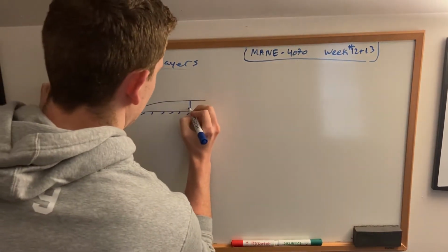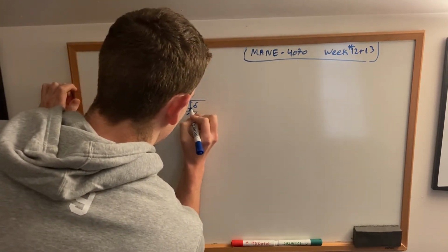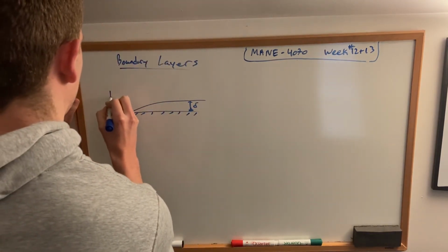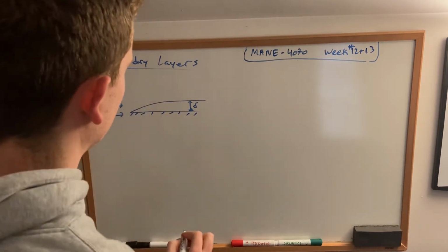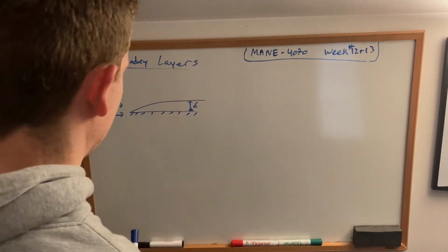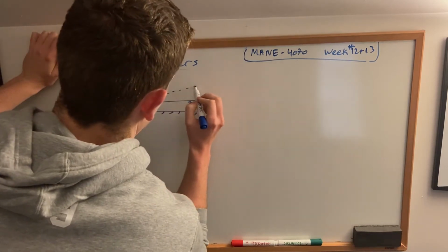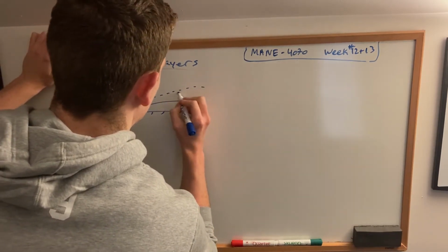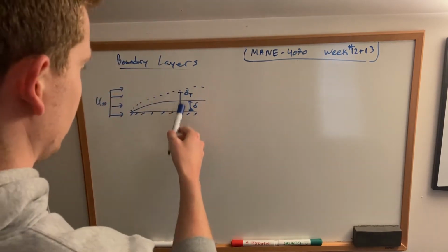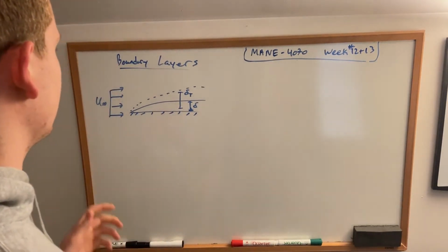Boundary layers being defined as the height of the area above some surface in which the flow velocity is less than 99% of u infinity, as affected by the viscous dissipation from the wall. We can also define some thermal boundary layer with a similar definition that's generally higher, where the local temperature is within 99%, or not within 99%, of the ambient temperature.